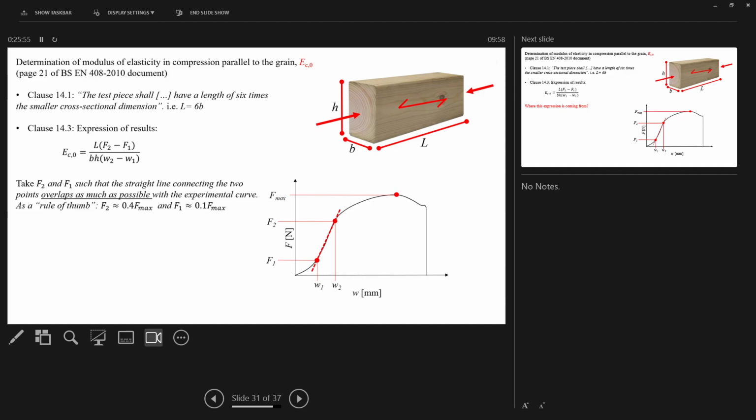We were talking about the linear elastic range. What we should find as we test this is that between 40% and 10% should be a linear elastic range. It won't be perfectly linear elastic, but it should be pretty good. And what we'll do is something in Microsoft Excel, we'll be doing it today actually in the tutorial, and we'll get an equation of that linear straight line.